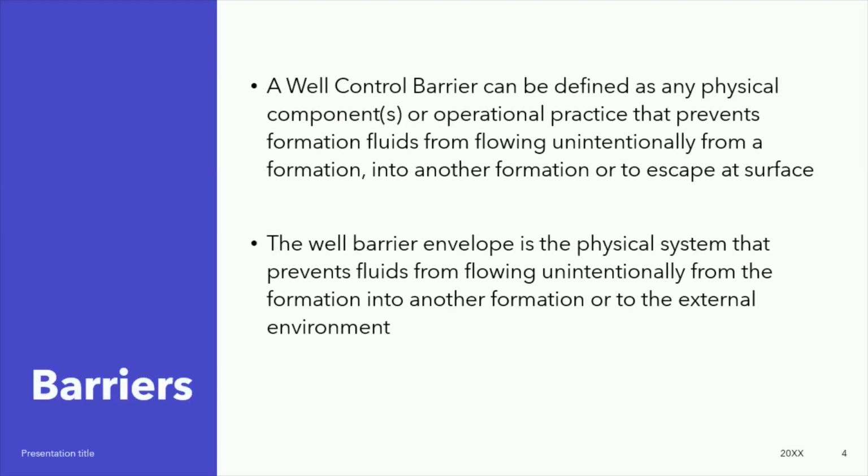Concept explanation. A well control barrier can be defined as any physical components or operational practice that prevents formation fluids from flowing unintentionally from a formation into another formation or to escape to surface. The well barrier envelope is the physical system that prevents fluids from flowing unintentionally from the formation into another formation or to the external environment.